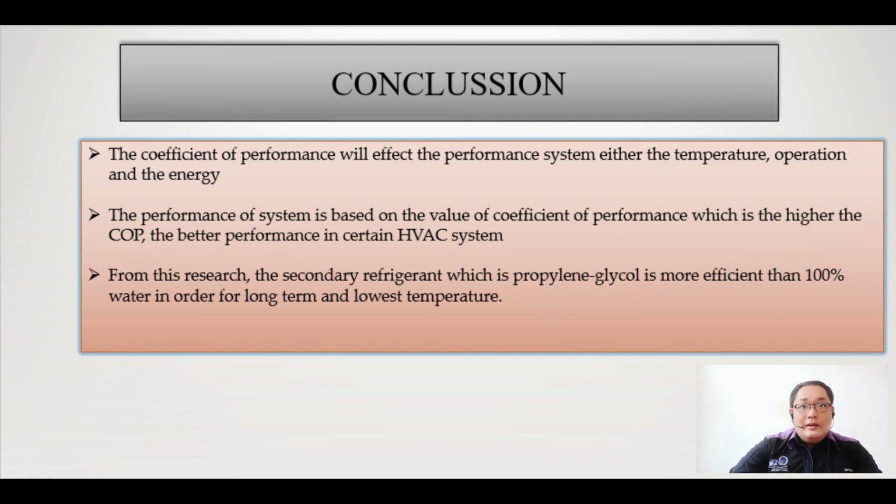Okay, third, from these results, we used two mediums as secondary refrigerant: 100% water and also a propylene glycol mixture with water. So propylene glycol is more efficient than 100% water for long term use or lowest temperature.